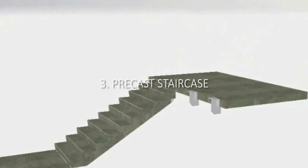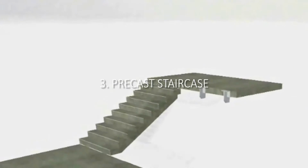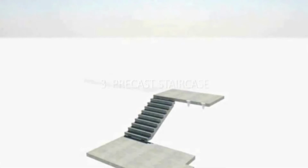Precast staircase is manufactured from bespoke molds and can be produced as straight flights with separate or attached landings. Steel brackets are bolted to the foundation using concrete anchors. These will be used to catch the legs at the back of the stairs.